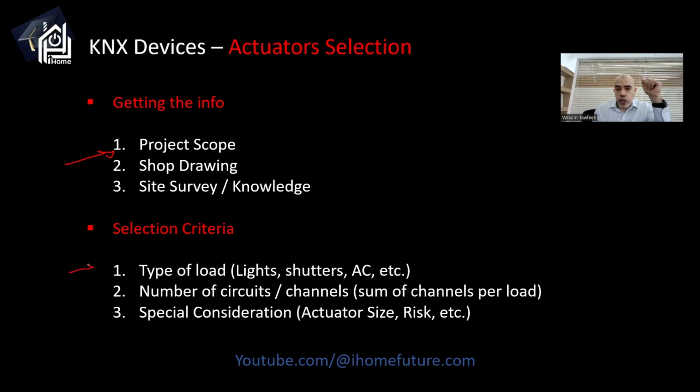Okay. So how could I number the actuators? I need to find out the type of load. So a light actuator is different than a shutter actuator. Then I need to find out how many circuits there are for this load. So if I have, let's say, 16 circuits for lights, then I need to get a light actuator that will work as 16 channel, something like that.